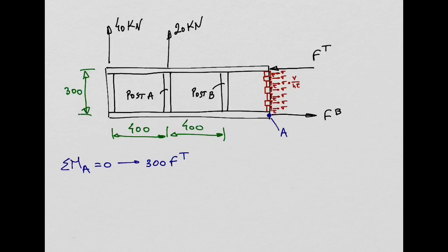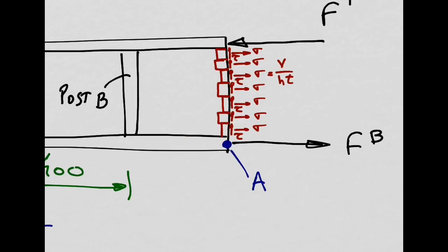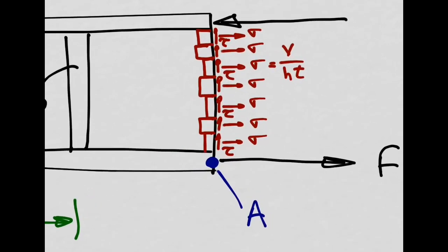We have the moment produced now by, look, if you look at the shear stress tau, the shear stresses are passing on that point A, so the moment produced by the shear stresses is 0, right? But the moment produced by this sigma stress, direct stress, is not 0. Yeah? So you need to look at this sigma stress like if you have a distributed load on the web. Okay?